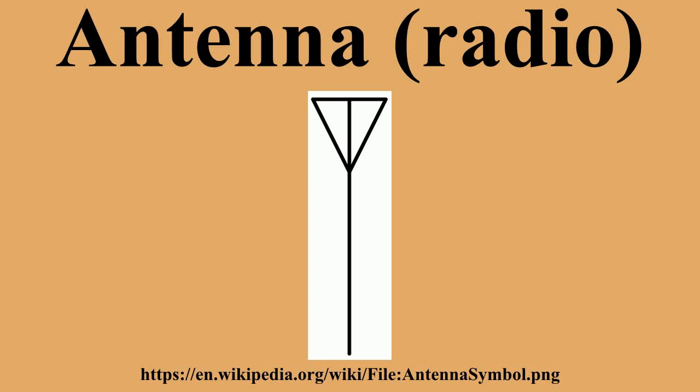These are employed when the relative position of the other station is unknown or arbitrary. They are also used at lower frequencies where a directional antenna would be too large, or simply to cut costs in applications where a directional antenna isn't required. The other category is directional or beam antennas, which are intended to preferentially radiate or receive in a particular direction, a directional pattern.